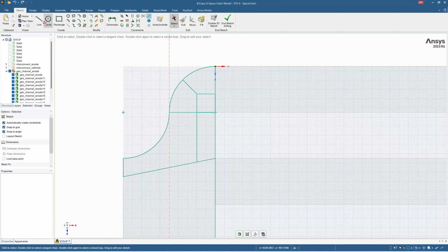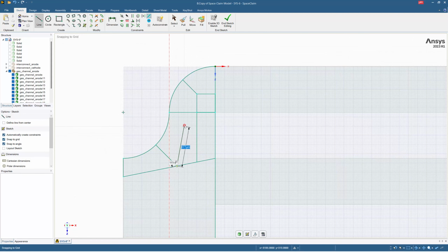So in order to have a better mesh quality, we should always divide the arc from the central point to here, and then from here we have another division from the same node to the center point of this.